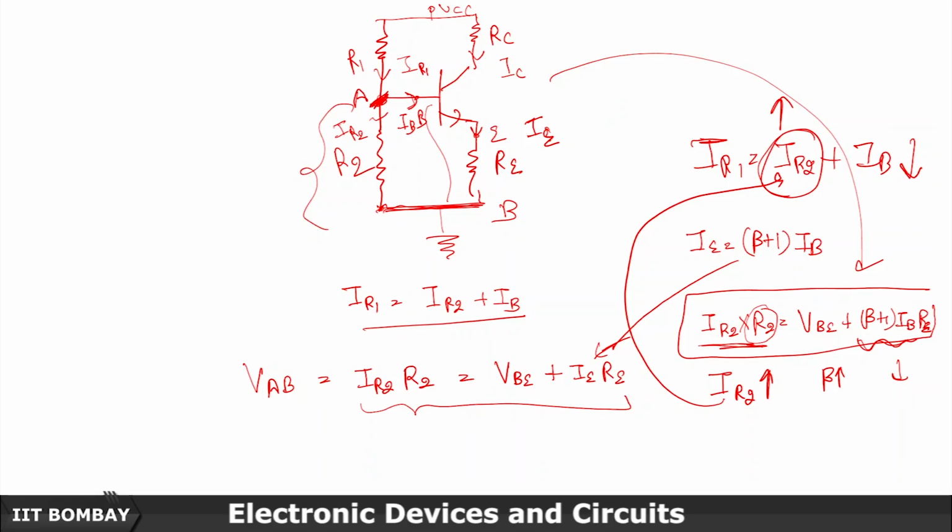So, that is why this voltage divider bias configuration is better than the emitter bias configuration. There is no such feedback mechanism in case of an emitter bias configuration. So, let me draw all these three diagrams together, the fixed bias, emitter bias, voltage divider bias, so far what we have discussed, just to have a comparison of what is going on.